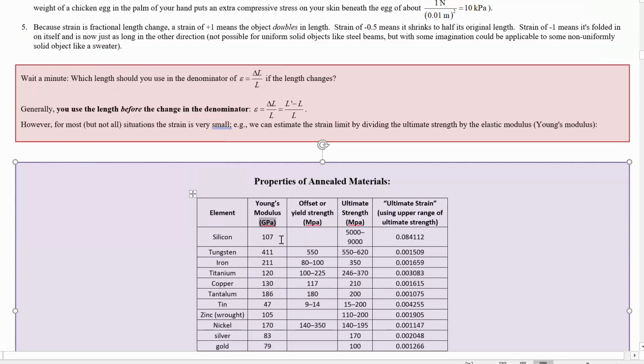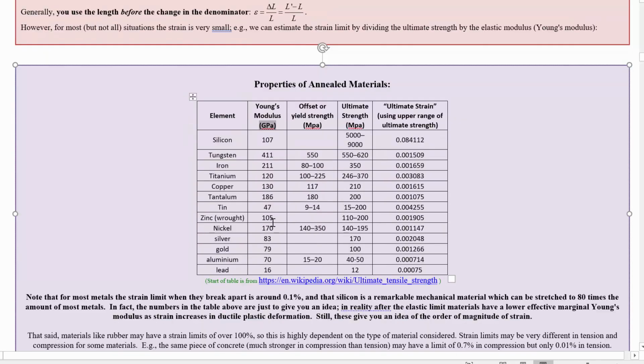So what does that mean? It means that if you push on a cubic meter of lead and you want to move it by 1 micron, you want to push in on that so that it's going to move by 1e-6 meters, you are going to need a kilonewton of force for every gigapascal that you have in its stiffness here.